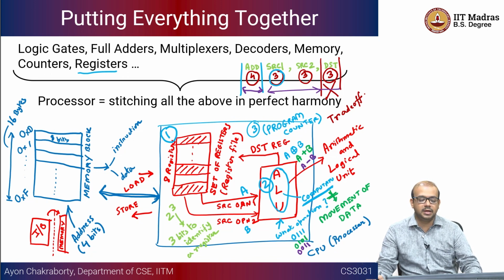Okay. So, it could be making the microarchitecture very complex. So, for example, you can have a circuit that does multiplication, right. In that case, the instruction is very complex, but it is just a single instruction, right. Whereas you may have a simpler circuit, and the simpler circuit is only going to do addition. Of course, addition will take less time, but you have to do many additions to achieve multiplication, right.